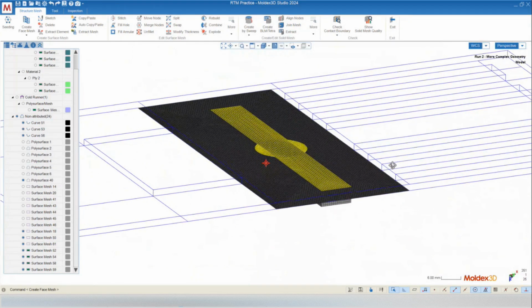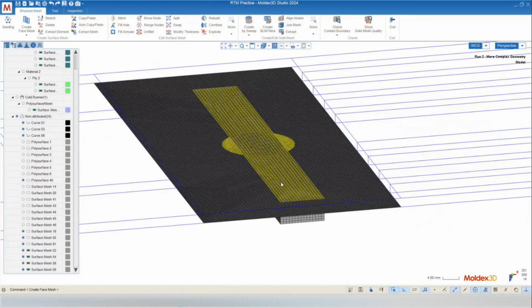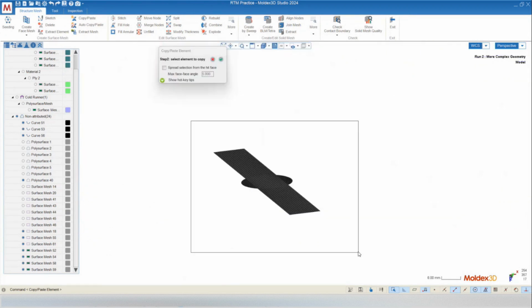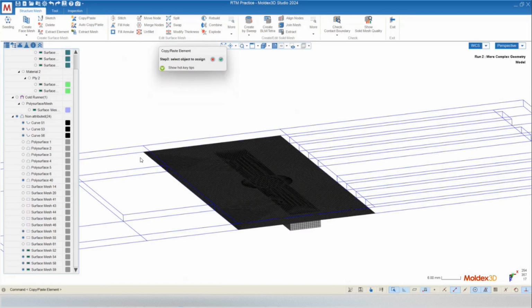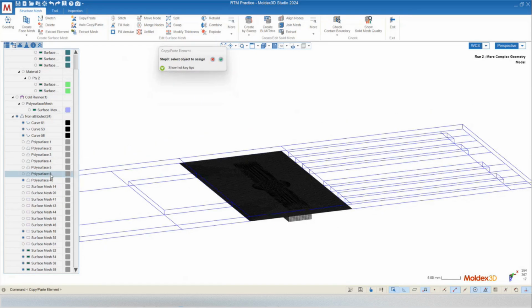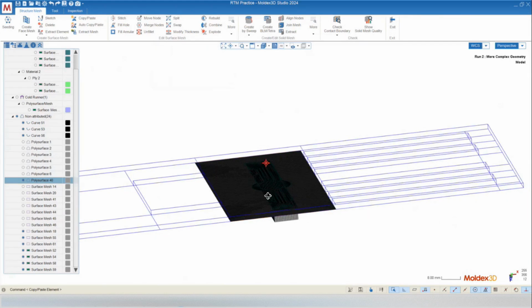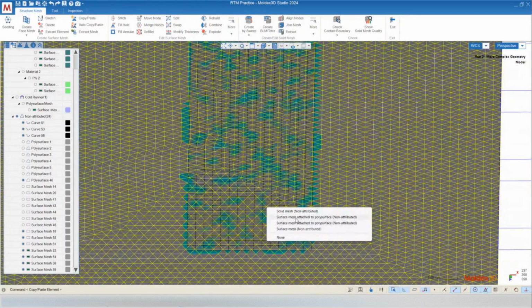Yeah, I think we have to do that copy paste again. That surface mesh that we copied over got removed when we did the node seating. So we'll do that copy paste one more time. You can select that surface on the bottom side of the cold runner. All right, select all of the elements, check mark. And then we'll select the geometry, which we'll probably have to do from the model tree. And once that's selected, you can hit the green check mark. And you should see a bunch of green elements now. Those are actually overlapped with one another.